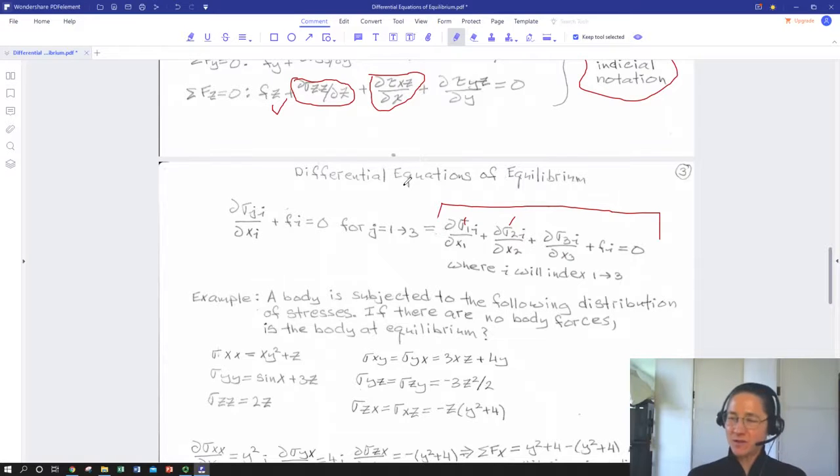So this kind of cinches our concept of stress at a point. We've looked at average stress. We've looked at shear and normal stress on a small area that we can define and for which we can resolve the vector. We've looked at how shear and normal stresses change as we look at a given plane, a given small area in a body, and then rotate that with respect to the direction of applied stress and maybe an external coordinate system.